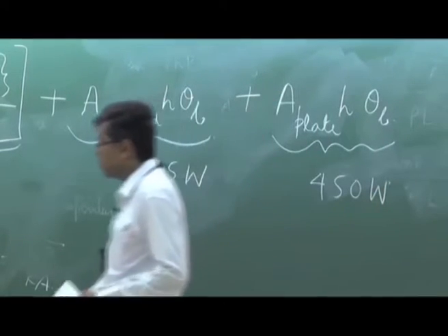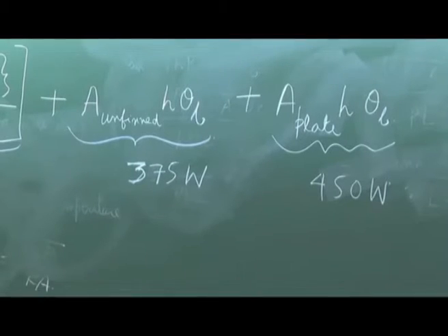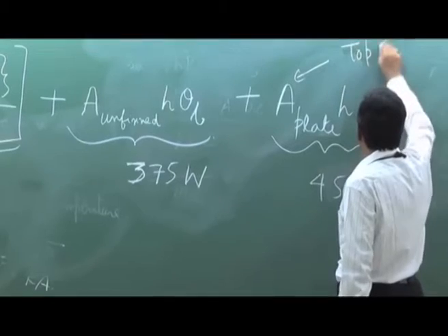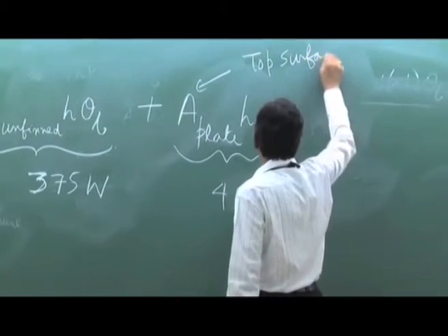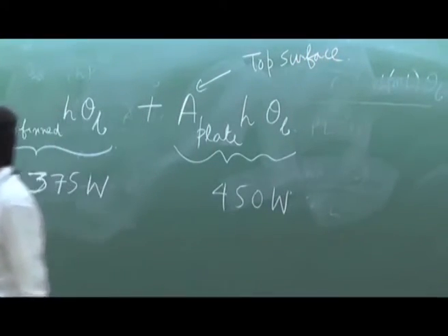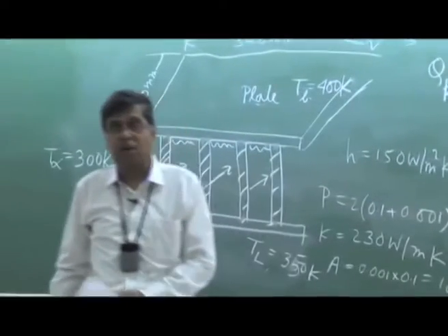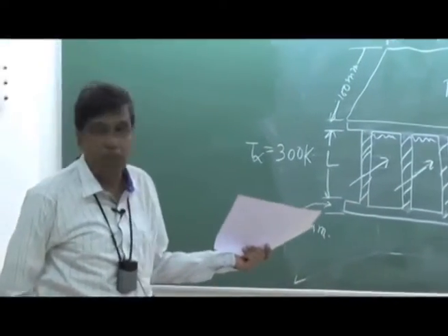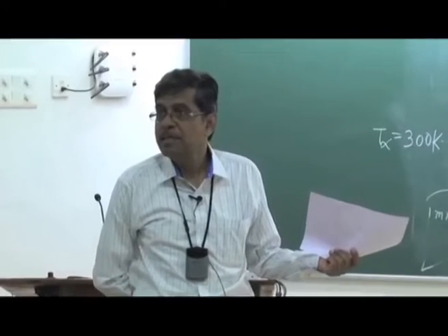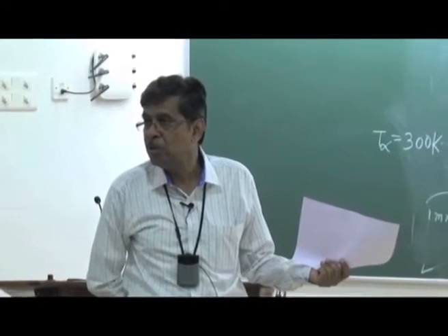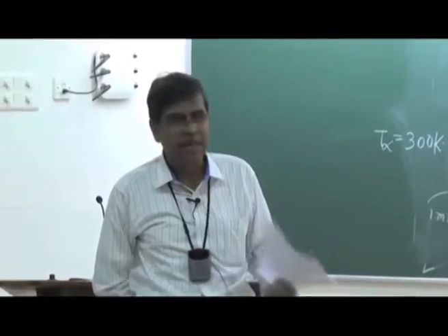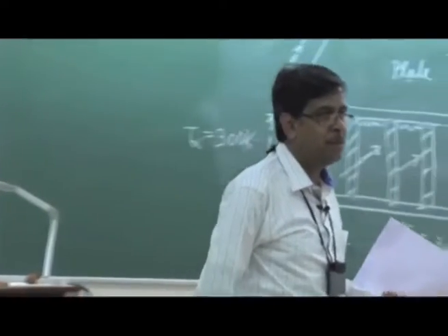A plate means the top surface. Now one comment I would like to make: you see most of the heat transfer takes place through the fins. It is increased by an order of magnitude. This is because of the huge surface area provided by the 60 fins.